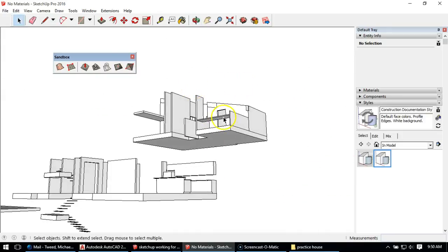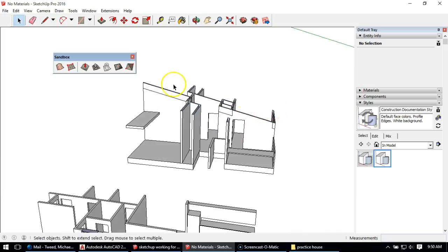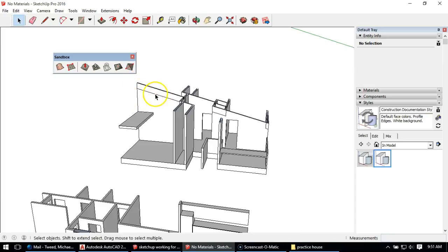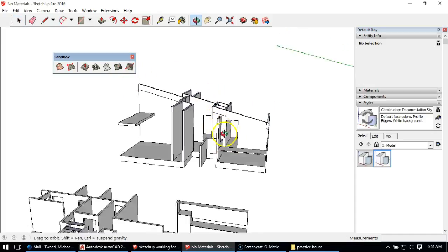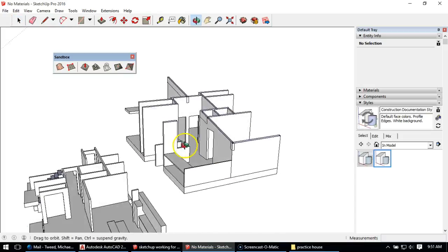We can see I actually even moved it up in this plane to help in elevation. And what I had to do for this part is copy the roof over and put it on this section. So I extruded the walls tall, just like I did the exterior model. And I did Intersect with Model, and then deleted those walls so that they would sit underneath the roof. If you need help with Intersect with Model, then go see that video where I did it with the exterior walls, because it's the same thing, I just did it with the interior walls here.